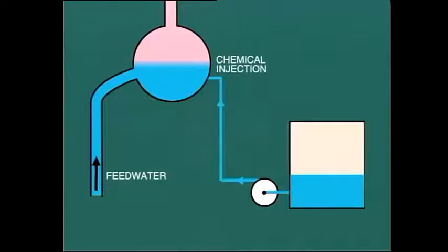pH values above this level may lead to caustic attack at certain locations in the boiler. It may even be necessary to use monosodium phosphate in some cases in order to hold the pH level down to the desired level.